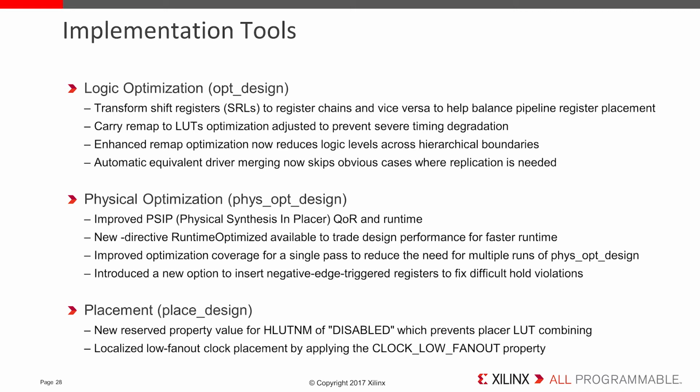A couple of new features in Placer include the EDIF LUT_NM property with the keyword of disabled, now preventing the Placer from combining individual LUTs when trying to fit a highly utilized design or P block. Up to this point, there had been no control over Placer LUT combining. This is important mostly for debug and ECO flows.